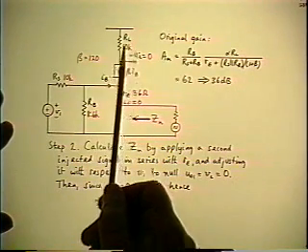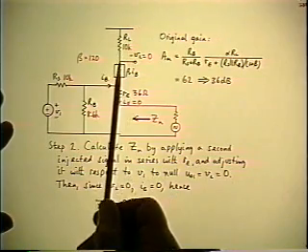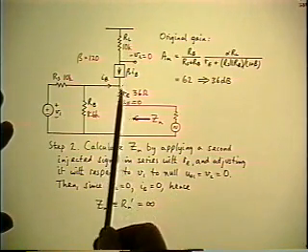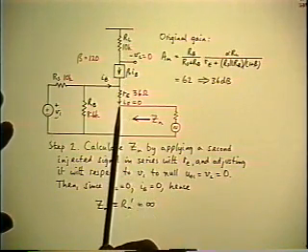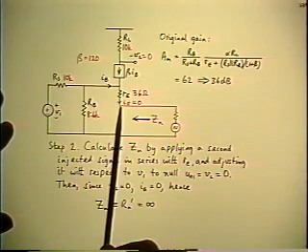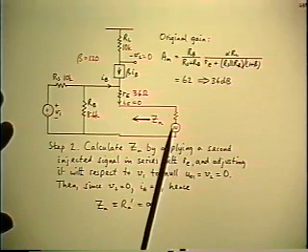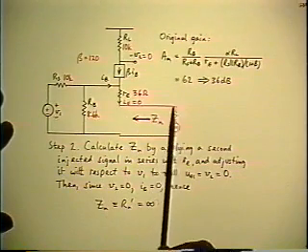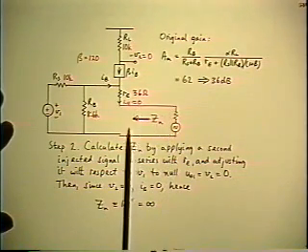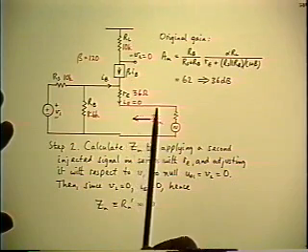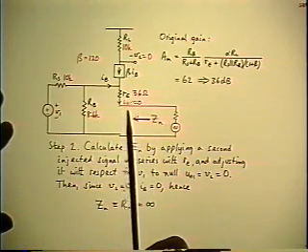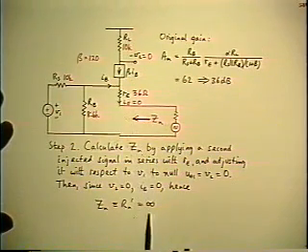If V2 is 0, you have 0 current in RL, you have 0 collector current, and you have 0 emitter current. And this time, the emitter current is the only current that goes through the second source. So the conclusion is that regardless of the voltage applied by the second source, 0 current is drawn from it, therefore the driving point impedance is infinite.